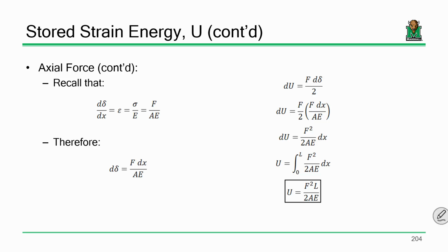So you think about it, if I have the stored energy inside a bar, which is the force inside that bar squared times L over 2AE, and I know the force that caused that stored energy, it's funny how I can set those two energies equal to one another and solve for the displacements, right? Pretty straightforward.